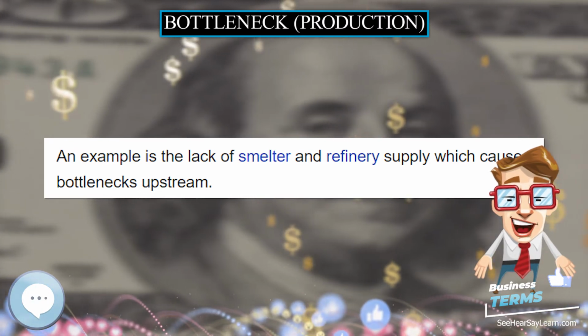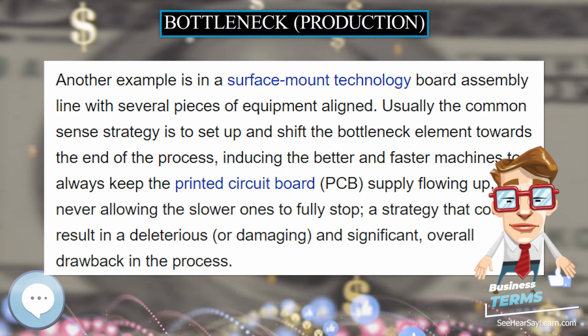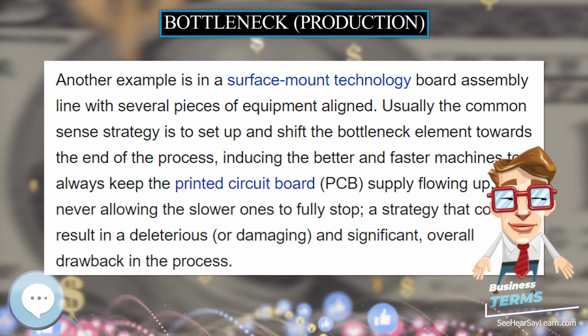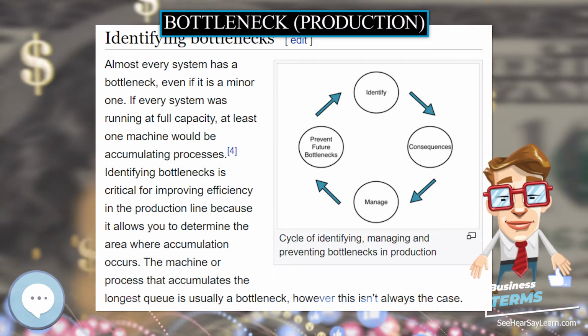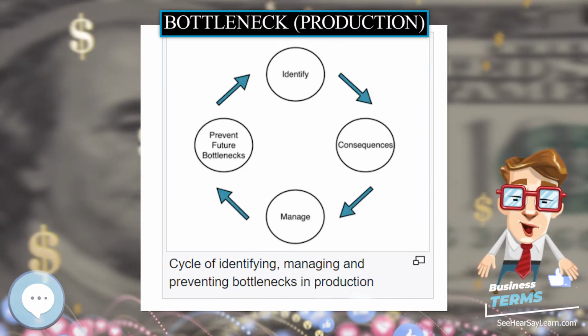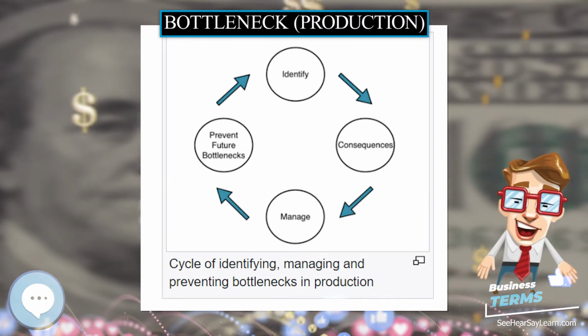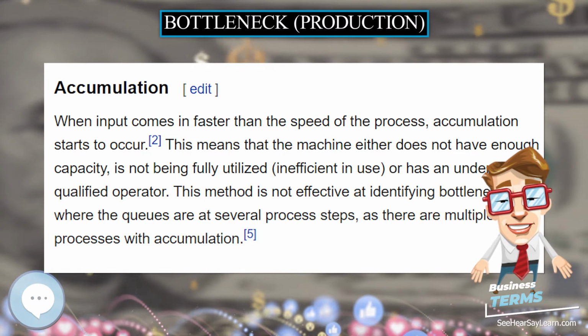Removing the waste operations results in a shorter cycle time, hence allowing the machine to complete each process in less time. Provide a constant buffer stock upstream. In order to optimize the usage of the machine, it should be kept running for as long as possible and hence should never have to wait for materials or stock, to increase productivity.